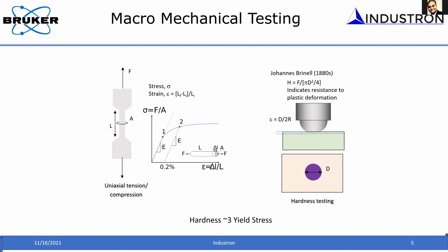One of the advantages of the hardness measurement technique is that it is very local, even at the macro scale. For example, with Brinell ball indenters, you can do an indent within millimeters. It's very local and very fast, and it's much easier than making a tensile sample and doing the test. So it's a very simple technique, and that is one of the reasons why hardness testing is very useful in industry as well as in academia.